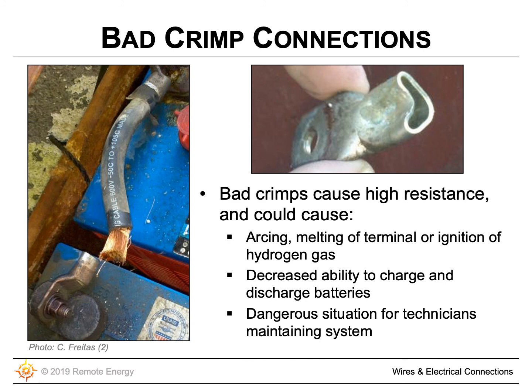And if it was in a closed container and you have a connection that potentially could be arcing or sparking during that period when it's charging very heavily, there's a real low chance, but potentially that could cause a little explosion, and we really don't want that to happen. So we're going to always crimp with the correct tools, and then we're going to check it. We're going to tug test that wire to make sure there's no possible way we can pull it out and that there's a good connection there.